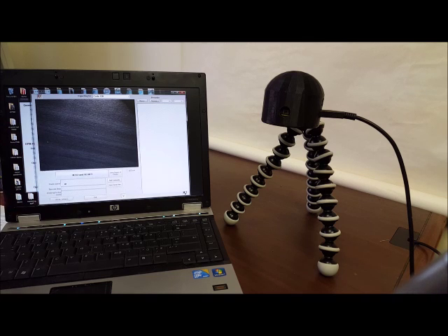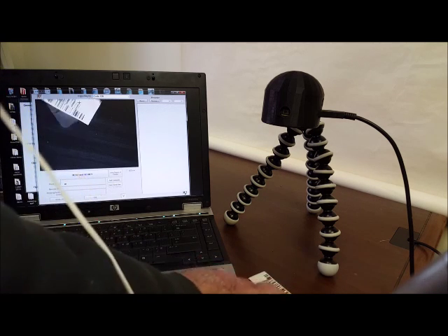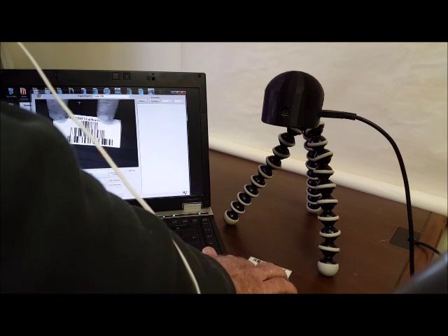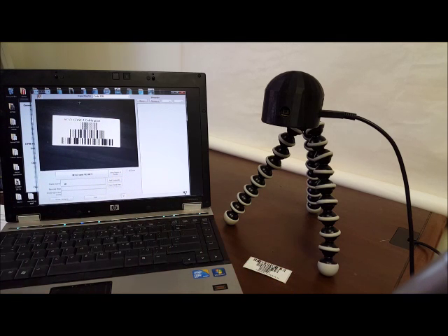When you first plug this unit in, like a standard USB, you'll hear the PC recognize the connection, the USB SCANALYST connection. You can start the SCANALYST software, which is now running. One of the first things you're going to do, if you haven't used it in this configuration before, is calibrate the unit. This is a trademarked calibration label that we designed for use with SCANALYST. You just place this label in the field of view, and you initiate the calibration procedure with one button. Pretty easy.